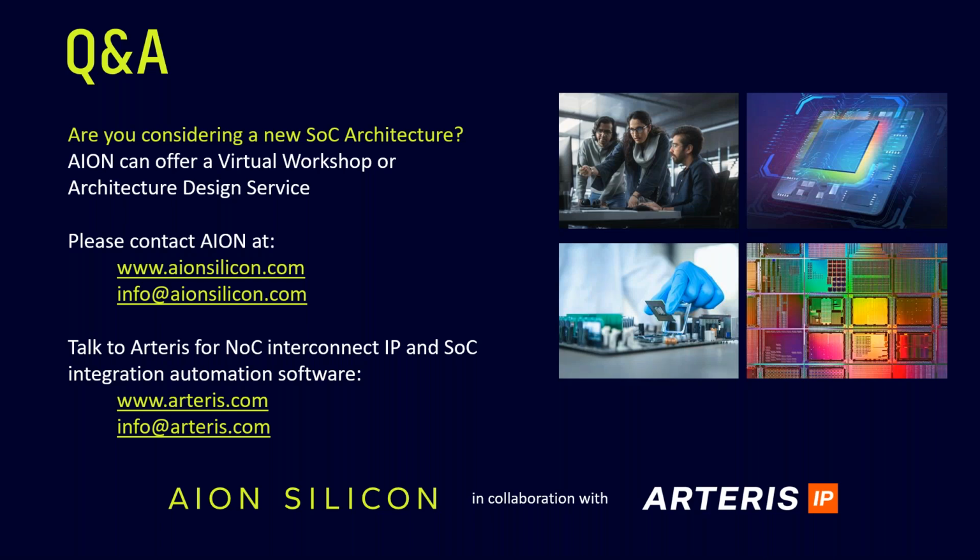Having said that, it is still possible to integrate the SystemC of your IPs within Platform Architect, and we've done that before. But it does affect your runtimes, and the whole point of performance simulations is you want a fast turnaround, you want your results back quickly. In order to make your topology changes or your configuration settings, you want to make those changes faster. So you need that immediate feedback. But yes, it is possible to integrate SystemC of your IPs within the full system simulation.